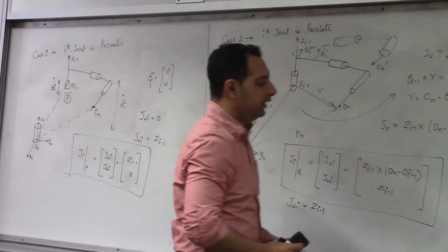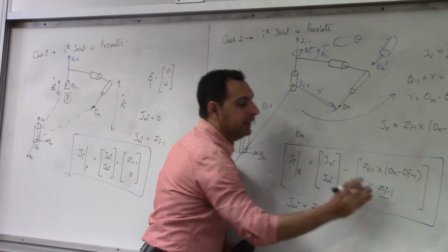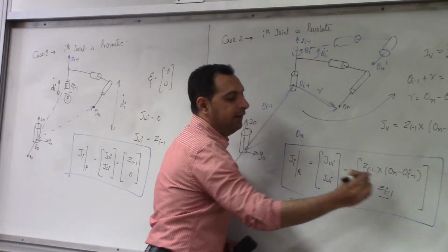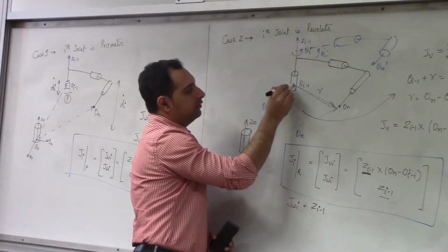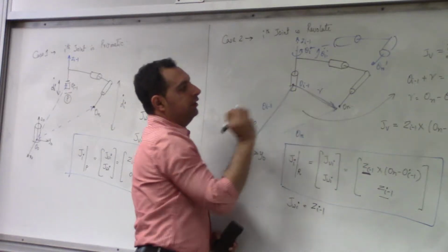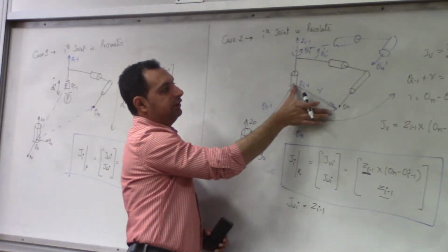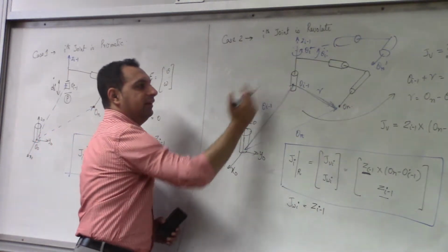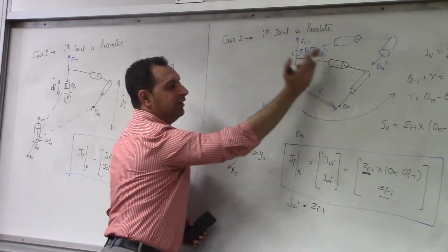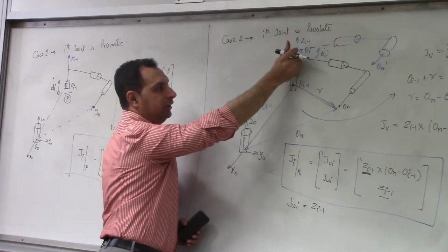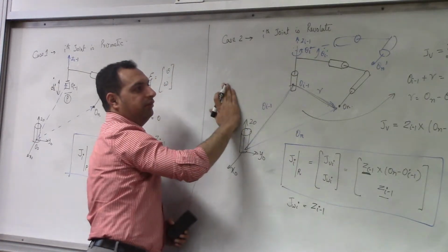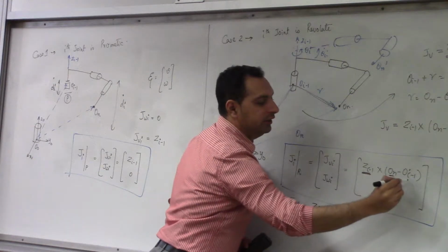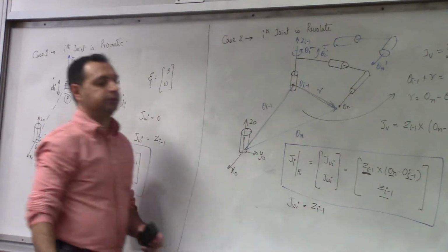That is how we do the DH table. So that will be Zi. In this case, it has to be a cross product between Zi and the distance R, which is from this joint to the end effector joint. So it takes into consideration all the intermediate joints, because anything before that is not affected, only the joints after that. If I'm generating motion here, the previous joints are not affected, the consecutive joints are affected. So this will be ON, your final joint, minus your current joint.